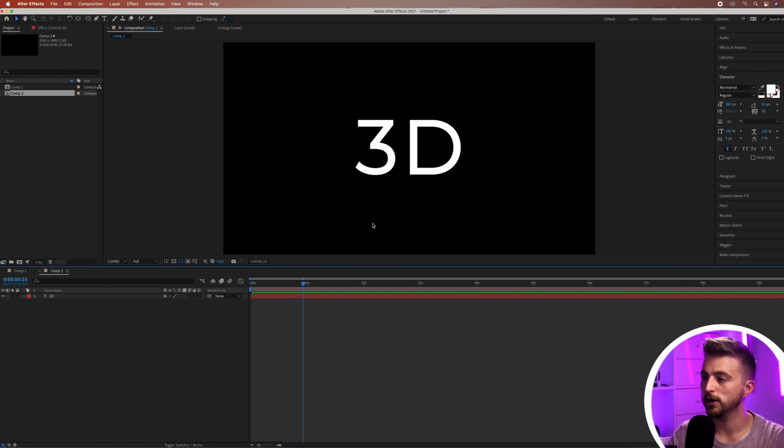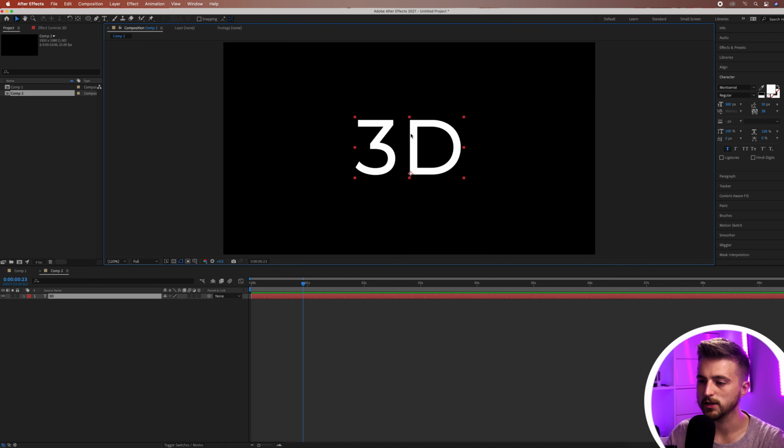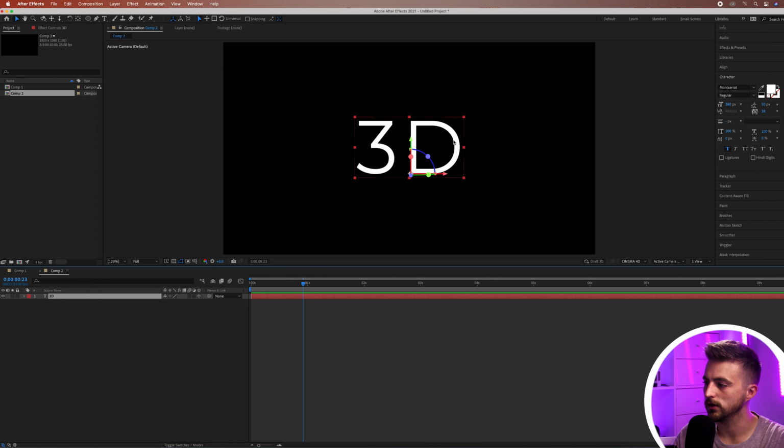Now from here, to convert this 2D text into 3D text, we just want to go down to this text here. So this is our text, and then scroll across. You should see this box here. This is your 3D text box. So you just want to select that. And as you can see, that has changed the look of this.